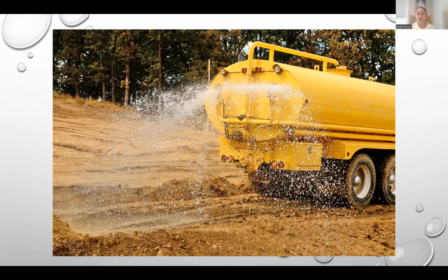And this information will be available later, but there are some important points I want to touch on. If you are doing a hydroseed application, we use a maximum of 10 pounds of PAM per 1,000 gallons of water, because when we mix the PAM and the water, it can get so viscous. If we use too much PAM in the water, you can form a very thick, viscous material that can clog equipment. So it's important to make sure that you're following the labels of any manufacturer when you're using the material.